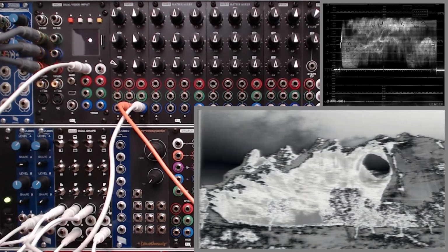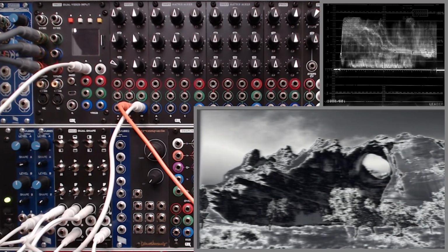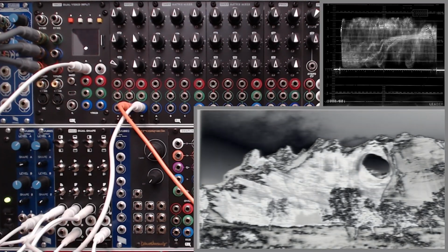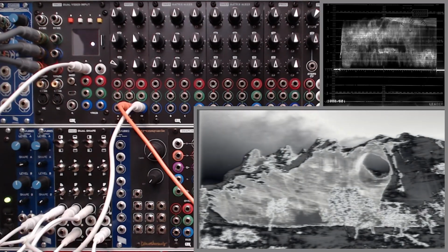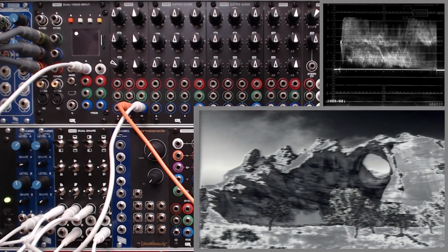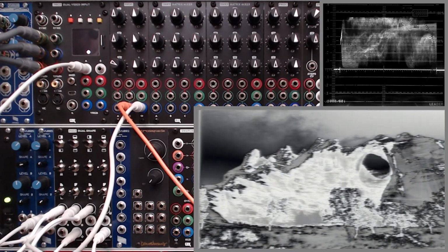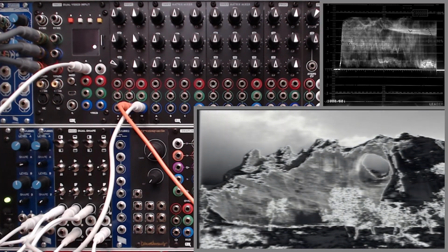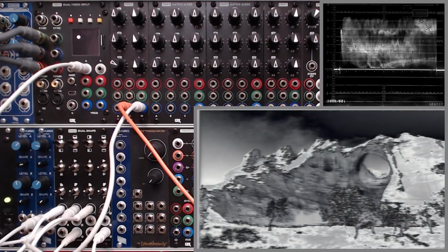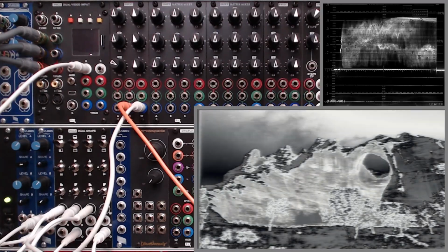Those are the ingredients. The basic path is you're going to combine your video image with a low-frequency sawtooth, find its absolute value, and then pipe that through a rectifier. You may also need to use a processing module. You see I've got a proc here in the mix, and that's necessary because to get a clean cycle, the amplitude of that low frequency oscillator is extremely critical. You may need to spend quite a lot of time actually tweaking the amplitude of that LFO in order to get a clean cycle.